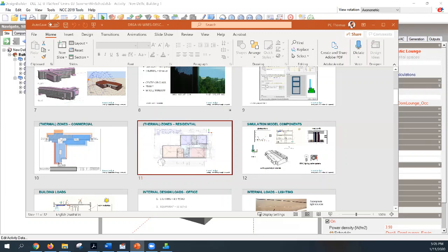So, will there be a zone division for radiant cooling systems? Zone-wise division. I'm sorry. Yeah. Well, look, there should be a zone-wise division for any type of system that you design. The reason you do this division is because a zone has a different thermal response compared to another. If you are able to make your building such that there is no difference in the load between zones in the center and zones in the perimeter, then you don't need zones.